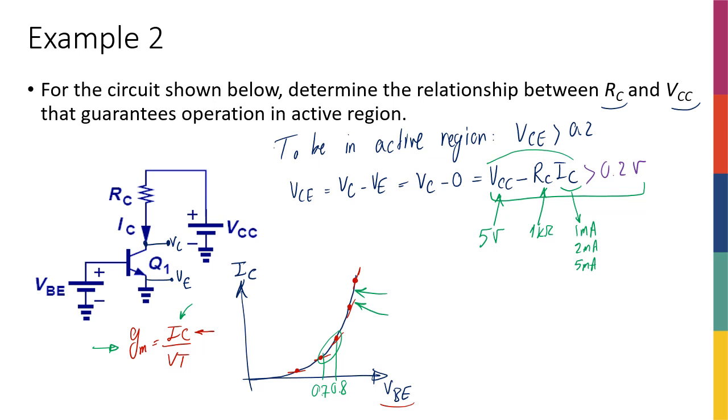Not actually having any kind of amplification because it's not a transistor anymore. We saw that it's not really a voltage controlled current source anymore. Okay, you might wonder, well, what will happen? I can still increase this current. If you are very curious, you might say that I can still increase this current and decrease the resistor, and keep the multiplication constant, therefore I'm going to avoid going to the saturation region. And that's actually correct. You're not going to go to the saturation region.